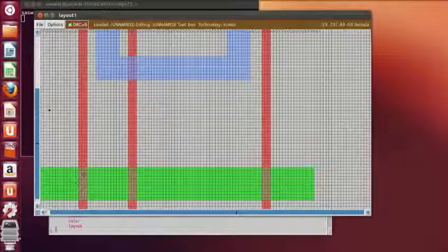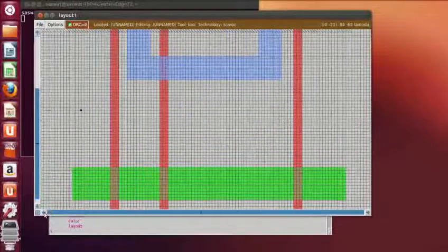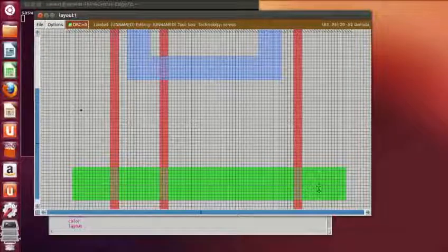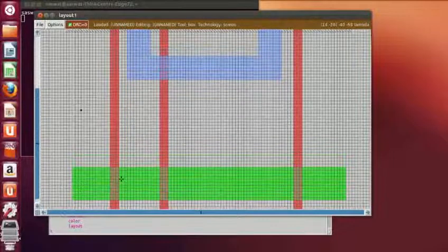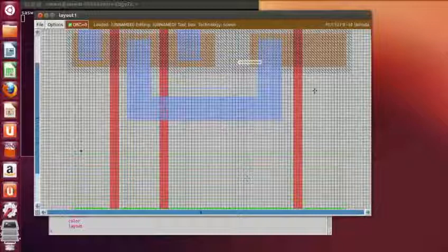This is the NMOS part. In the NMOS part, the drain of the first NMOS and the drain of the last NMOS, that is the third NMOS, are not connected. The source and drain are shorted, and this drain is connected to the drain of this PMOS.